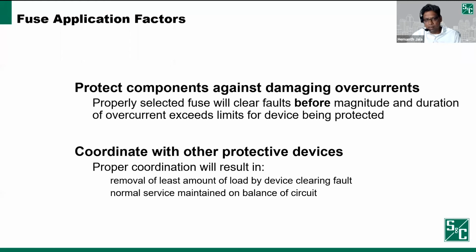And then the second part is you want to make sure the fuse coordinates with the other protective devices on your system, like we looked at with the 65K and the breaker example earlier. This will ensure that you'll remove the least amount of load when there's a fault, and normal service is maintained on the rest of the circuit.